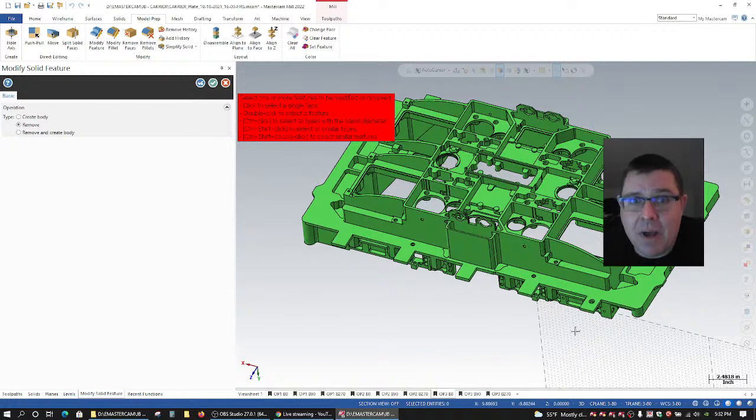And where possible, if you need that bolt head for collision detection, model a simple cylinder and use that in your fixture versus having the entire bolt that's really just sticking down inside the fixture plate. Anything that's inside the model, you don't need. It's only the skin on the outside of your fixtures that you care about for collision detection.